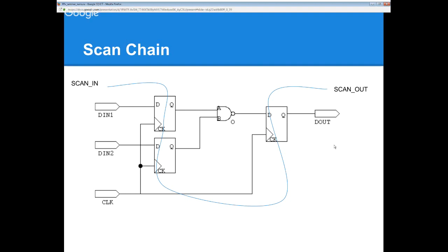So when we want to test some code here, in that case, we set some specific value to each register. Then observe the value. Then we can check whether this port is broken, or we can detect the defect of each port. So scan chain is a basic idea to check the logic correctness, to detect defects inside the chip. So I did such things after the Graph 6 project.